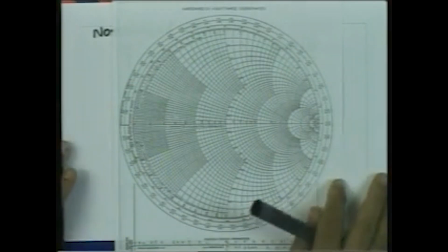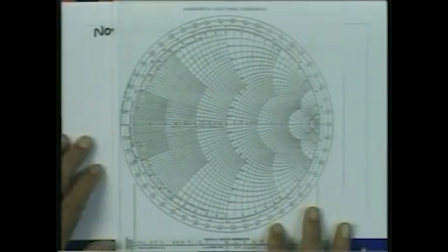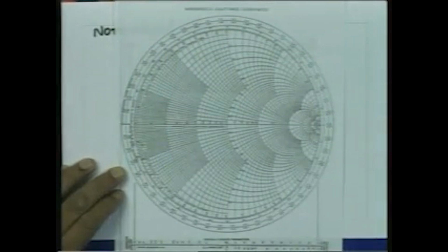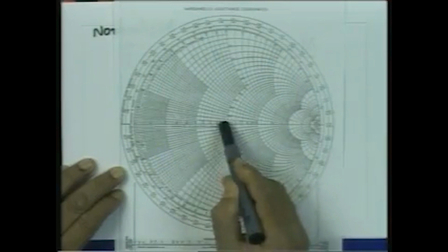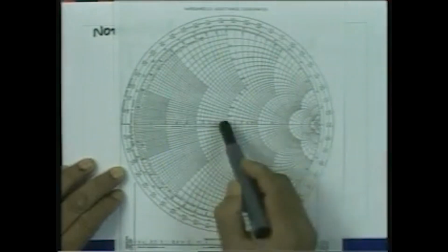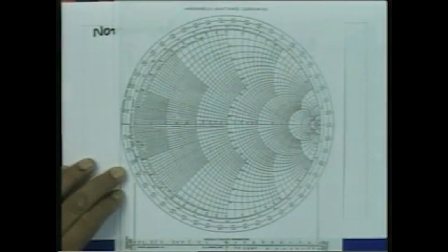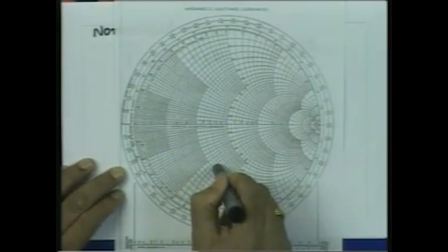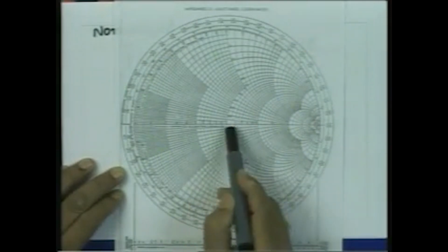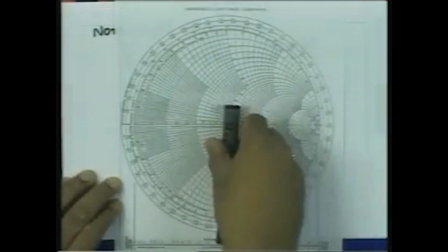So, if I develop an understanding that I will not rotate the Smith chart and will always use it in this form, that means the most clustered portion of the Smith chart is on my right. Then if I do the impedance calculations, the positive real axis is towards the right and the positive imaginary axis is upwards. However, if I do the calculation by using this chart for admittances, then the real axis will be on my left and the imaginary axis will be downwards.